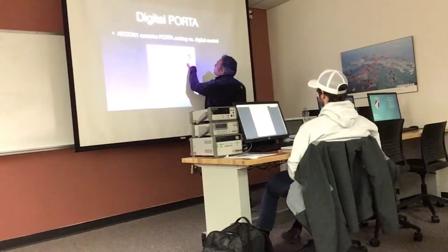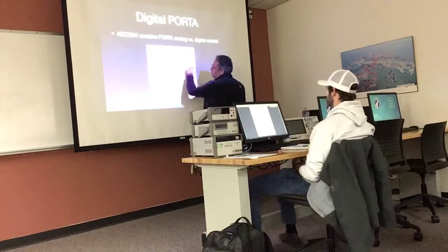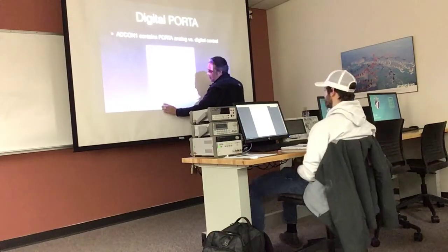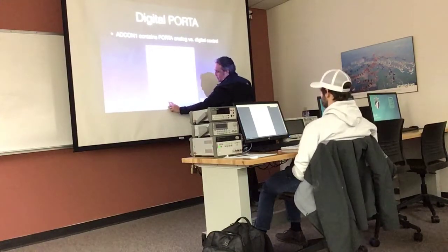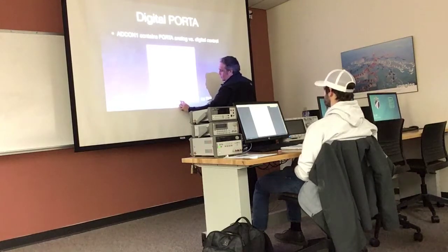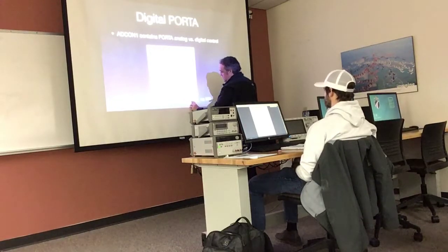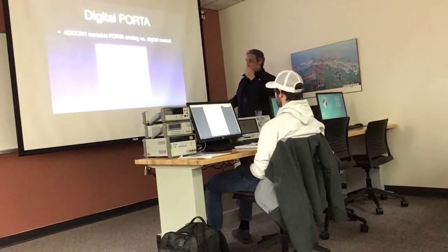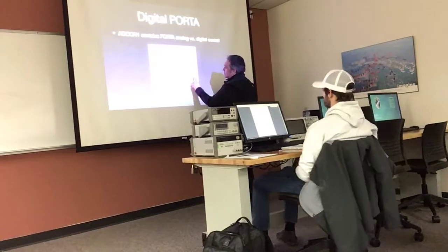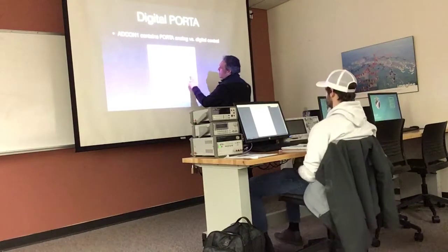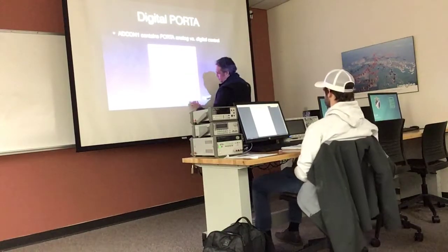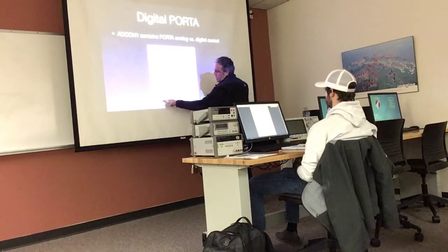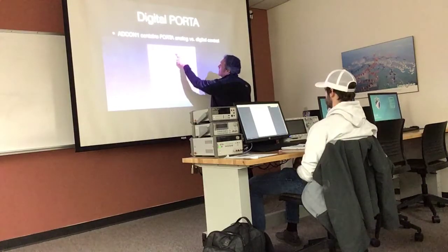Now check this out. If I put 1, 1, 1, 1 here, every single analog circuit will be configured as a digital pin. See that? Does that make sense? So, if you want 0, 1, 2, 3, and 4 to be digital, all of them, you're going to have to put an F in here.